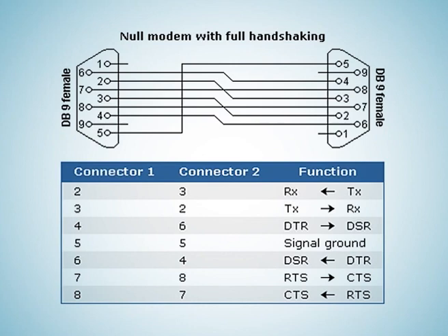Original standard projected a maximum length of cable between 2 nodes to be 15 meters, but by using a cable of low capacitance and good conductance, it is possible to get reliable communication up to 300 meters now.